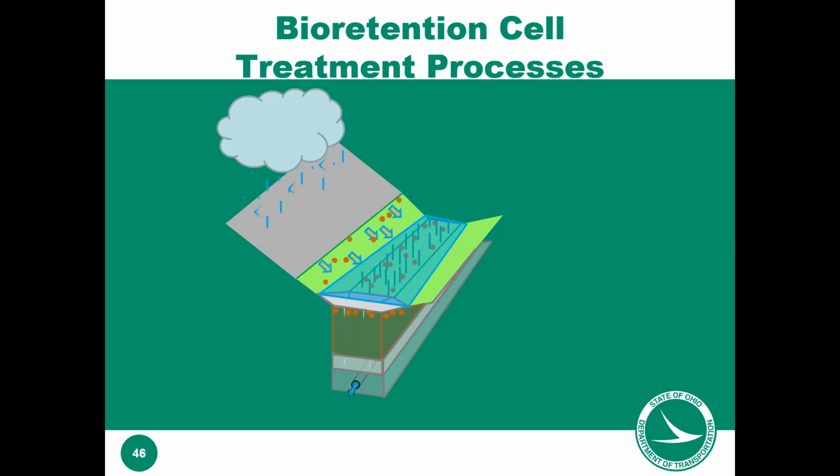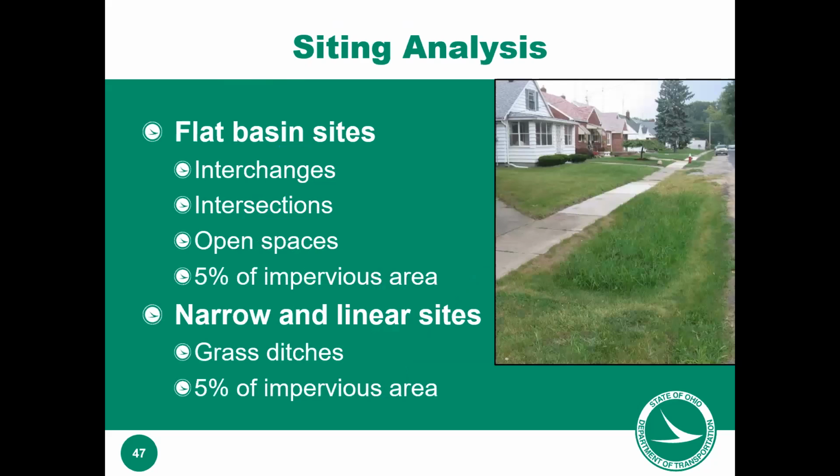So these fit in ODOT's world, almost any place that we have ditches on transportation projects, you can fit these bioretention cells. So a lot of times if we get pushed into that quality and quantity BMP world, these bioretention cells are a good option because they don't really take up as much right of way, and there's never more than a foot of ponding. So from a safety standpoint, they can be significantly safer than a detention basin that might have a few feet of ponding that you wouldn't want a car going into. You don't want a car going in this either, but it's significantly safer.